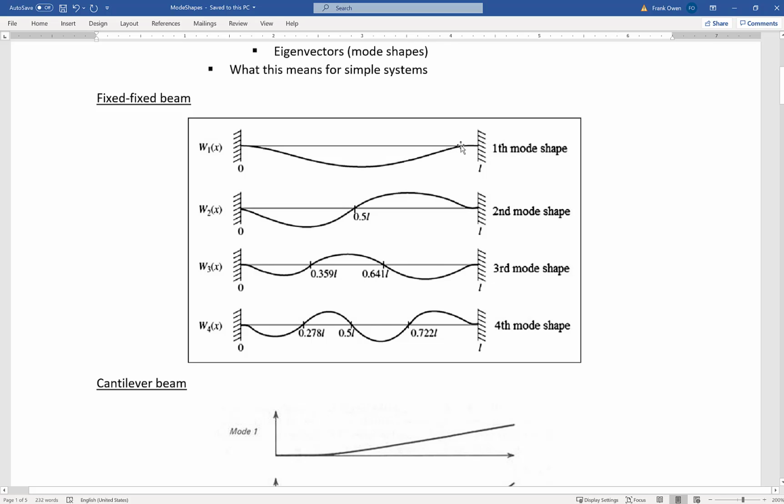So again, the way that these look, and we'll see it below with some examples, is that you have less bendy modes. That's not a good word, but I'll use it anyway, for the lower modes. And as you go up in modes, your bending gets to be greater and greater, the frequencies get to be greater and greater, but normally the amplitudes of vibration are less.